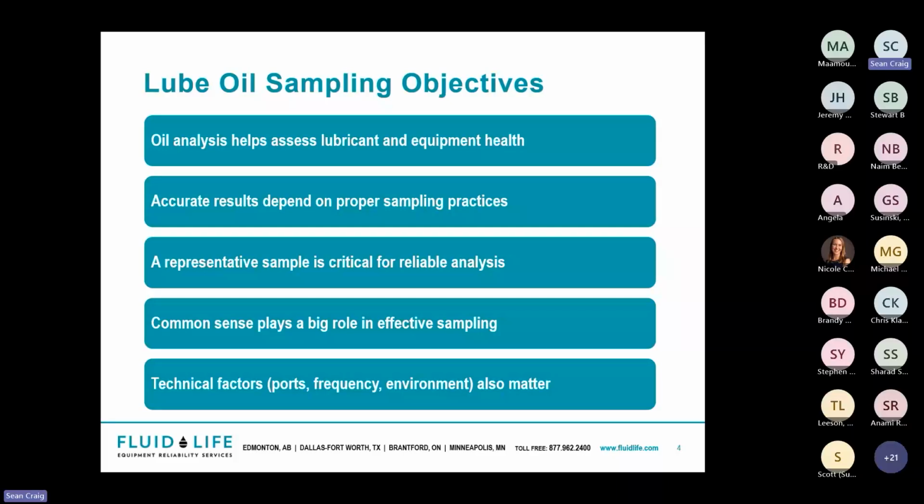So what does that mean? With one sample that you pull from your equipment, we can tell you if there's an issue maybe with the lubrication: it's acidifying, there's water, it's old, there's additive dropout, the viscosity is too thin or thick. Or maybe all that is fine, but there's something going on with the component, and excessive wear is being picked up. That could be a bearing that's off center and causing vibration issues. So everything could be fine with the oil itself, but the component maybe is encountering issues.